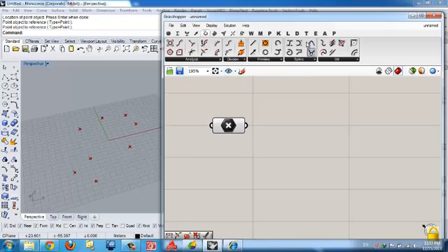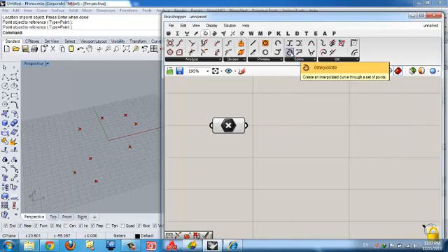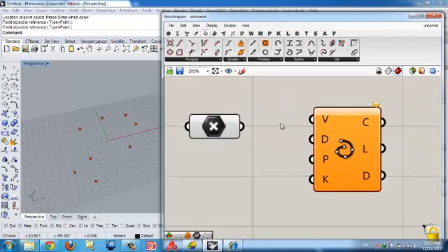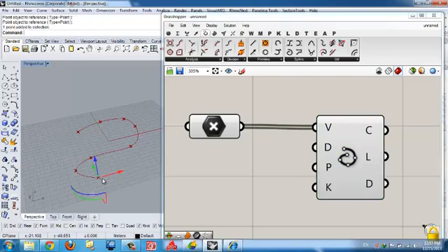So for the spline, you can draw curves and things by it, but the most simple thing is interpolate, that you just connect the dots together. So I put it here. You can see that it needs some vertices, so some points. I give this output to the input, and you'll see the curve emerging out.